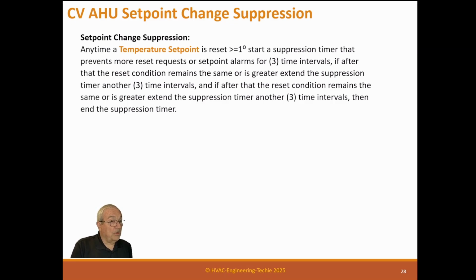That's what we're doing. We're only doing room temperature because that's the one that will affect energy the most, by requiring more and more energy to that air, even though the room may not be changing. So it's going to drive the set point way up. We'd rather have it modulate slowly instead of ramping up all the time. So that's what the suppression is all about.